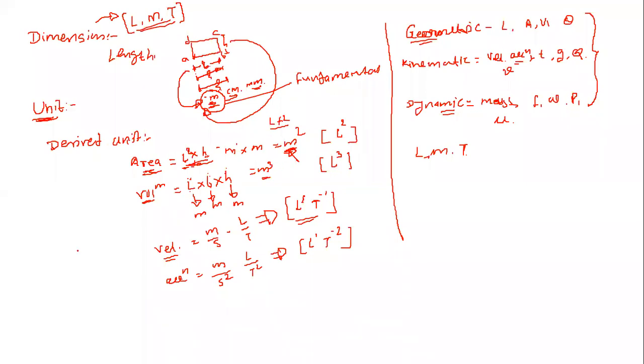The next thing is why to go for dimensional analysis and what are the various methods of dimensional analysis. Firstly, dimensional analysis is nothing but the formation of various groups of physical quantities so that we get a meaningful combination. For example, we write Q is equal to A V, the discharge equation. This is the combination of area, one physical quantity, and velocity, another physical quantity. If you combine area and velocity, we directly get discharge. How come we write that?